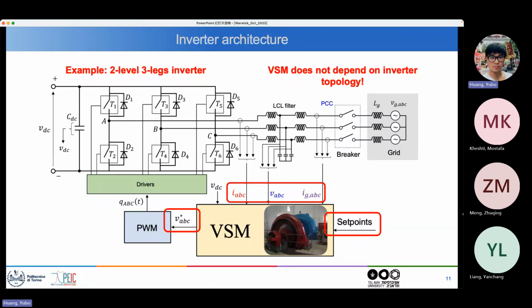So what we are proposing is only a software modification in the control algorithm of the inverters, which is now, I'm lying to you, it's not true, because you actually need a much bigger capacitor on the DC bus, because if you want to provide inertia, then you have to provide this energy reserve that is needed if there is a drop of frequency on the grid.